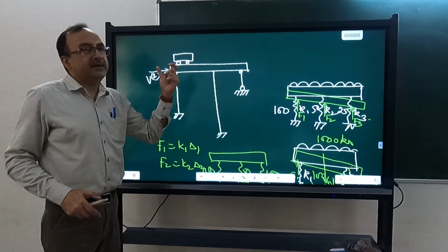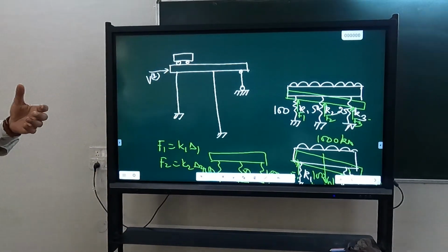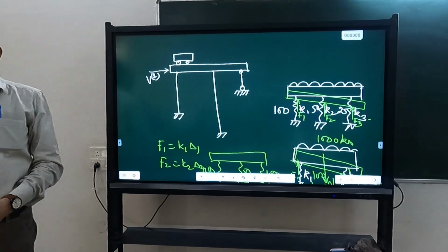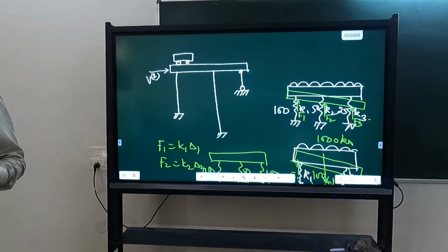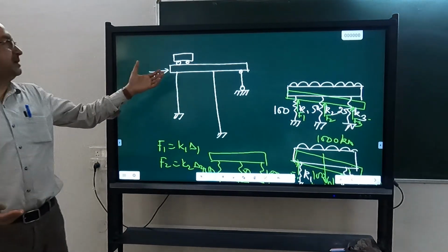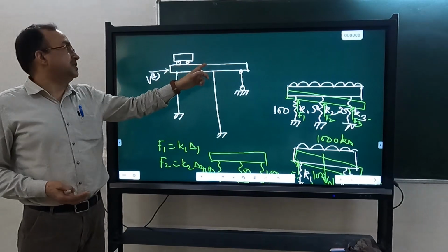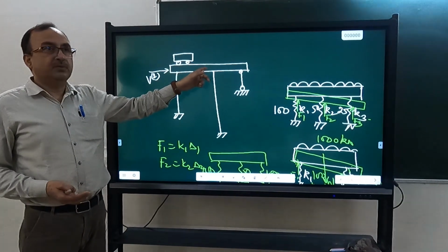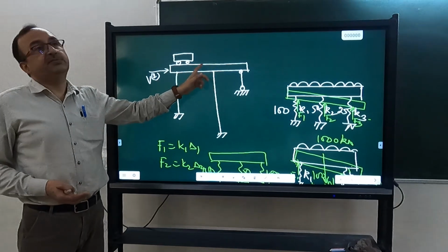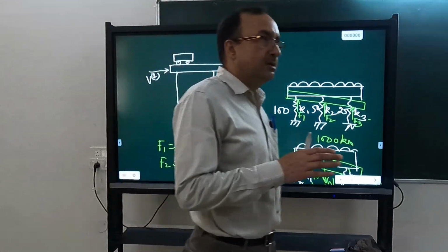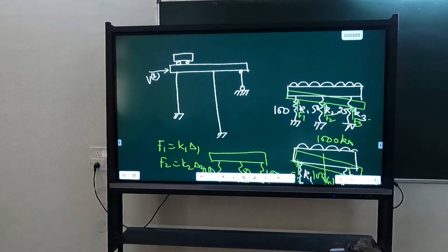So there is load and spans are very large. So due to this heavy load and large spans, superstructure is generally very strong. Okay, it has lot of inherent strength and it can't yield. But if it yields, then there will be shear failure. If the hinges are forming here, superstructure is yielding. So there will be shear failure, which we do not want. So superstructure we do not want to yield in case of bridges, and usually it will not yield. It will have so much inherent strength because of the gravity load itself that it is not going to yield.